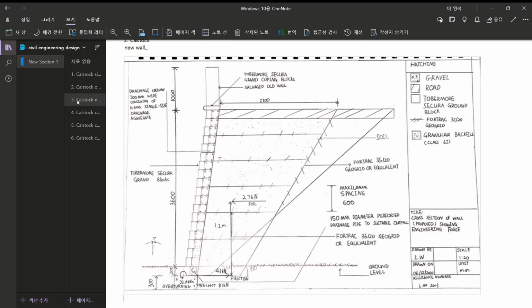Also, the geogrid reinforcement would allow the soil behind the wall to act as one singular mass by greatly increasing the frictional coefficient of the soil, providing added safety. Finally, to preserve the look of the area, we will construct a 1 meter fence on top of our wall out of salvaged old material, allowing the wall to have a continuous look.